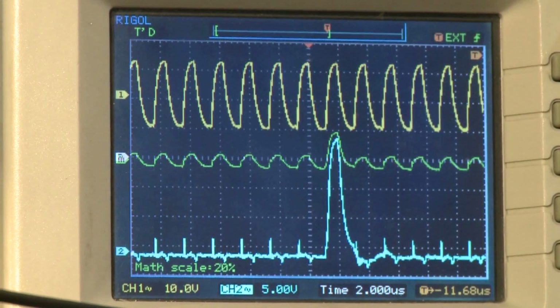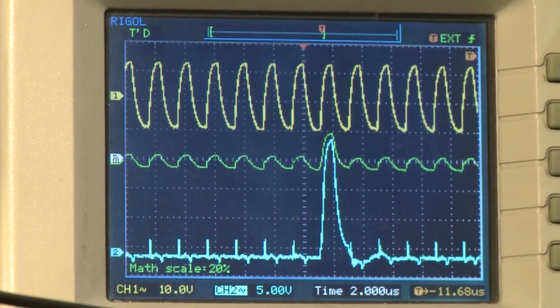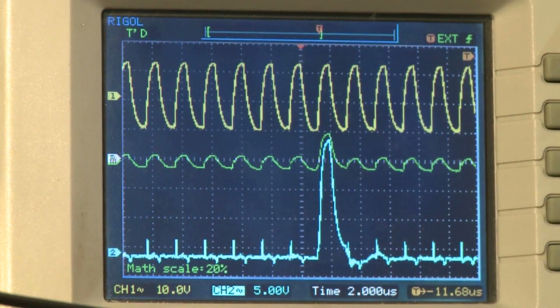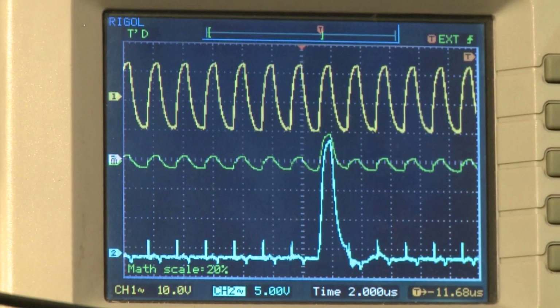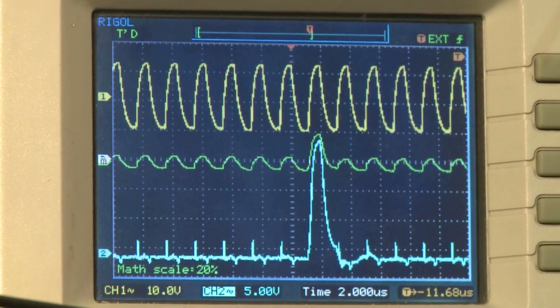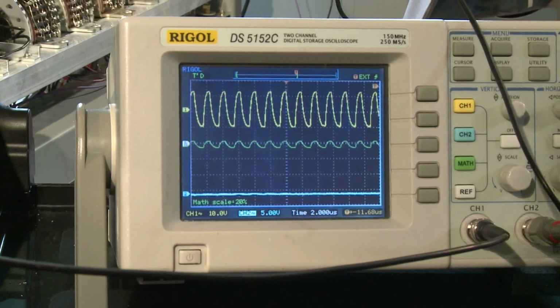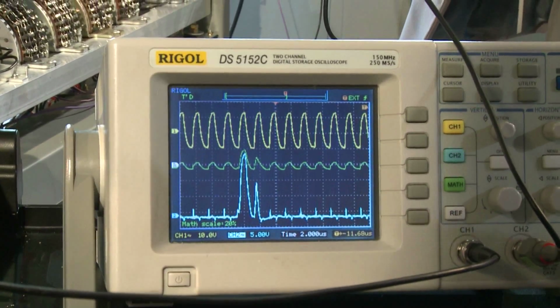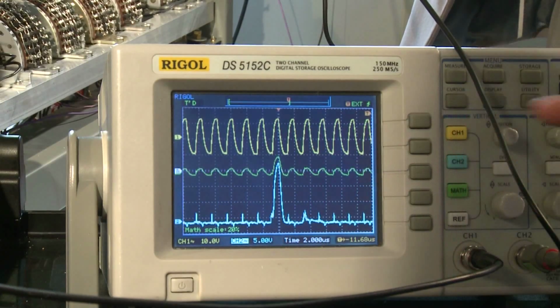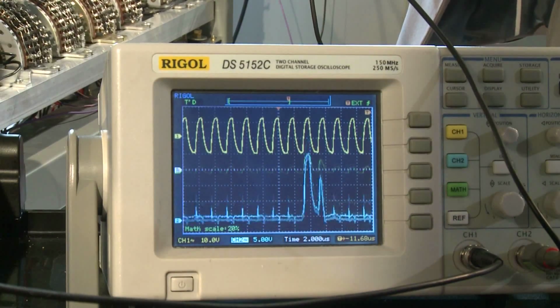So Peter, what we can see here is the clock pulse, very regular, running at 0.5 megabit per second, with the selective digit pulses, the blue ones below, and we can see that there is a sequence of those pulses, 36 in fact, within an EDSAC word, and those are used for selecting individual digits in a word.